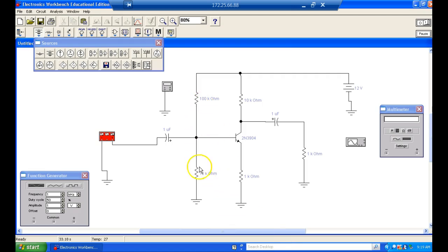So the higher we make these resistors, we know right now it's going to be less than 12K because this guy over here is seeing this times beta. So we know in a parallel circuit that your total resistance is always smaller than the smallest, right? You understand that?